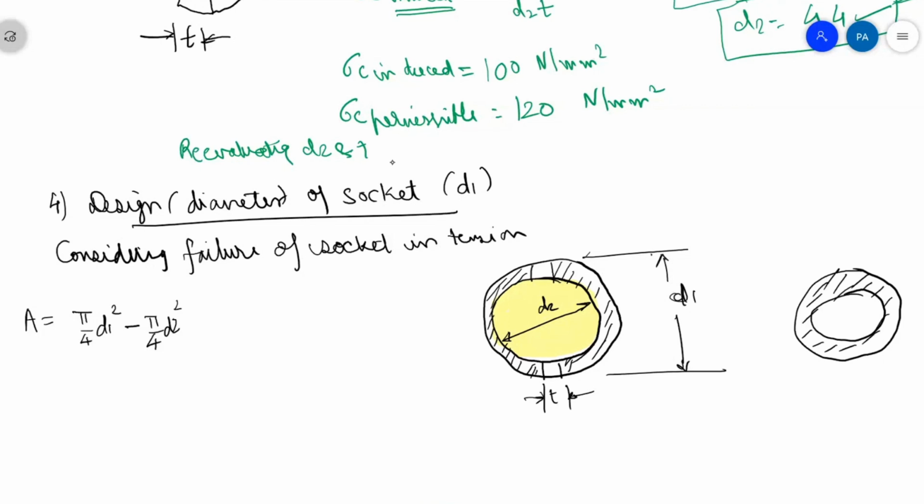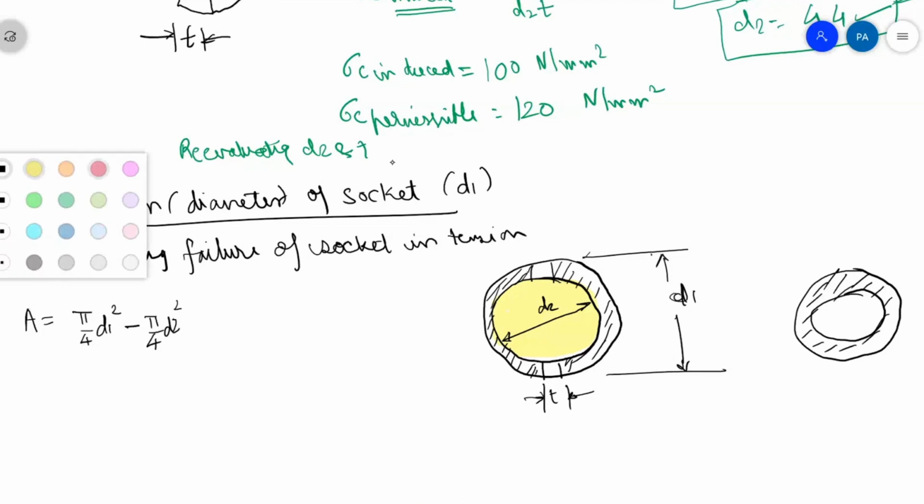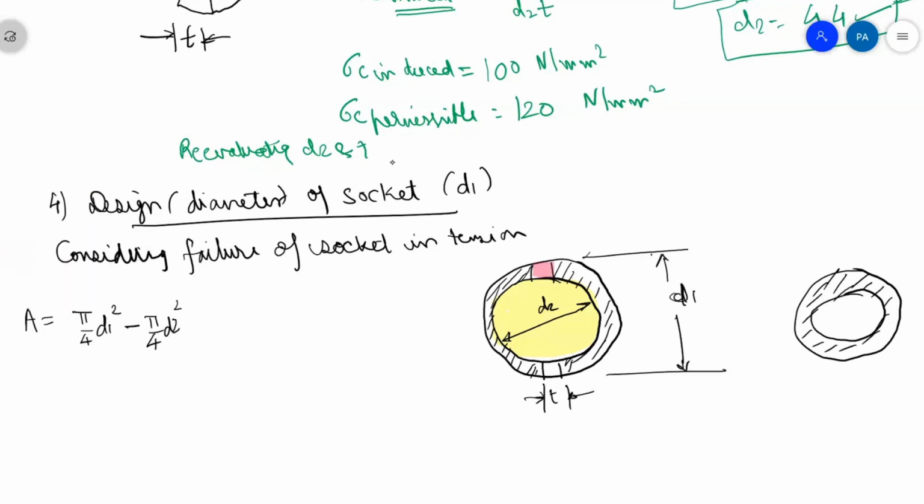And we also have to subtract this area. This area has to be subtracted and this area has to be subtracted. So how will we do that? Minus. Meaning, this entire rectangle, we subtract its area, minus d1 into t, and plus, we add this area, d2 into t. So this becomes pi by 4 into d1 square minus d2 square, minus d1 minus d2 into t.